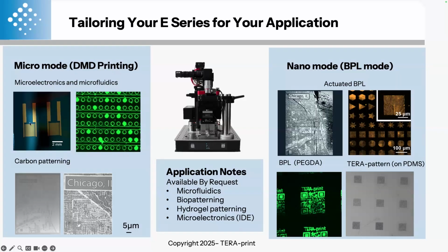Here, I treated the positive photoresist after patterning with e-beam evaporation to create a gold electrode, or you can use SU8, the negative photoresist, and create a PDMS, dPCR microfluidic device. Or if you need a conductive pattern, you can just use SU8, and after high temperature pyrolysis, you will have a conductive pattern.